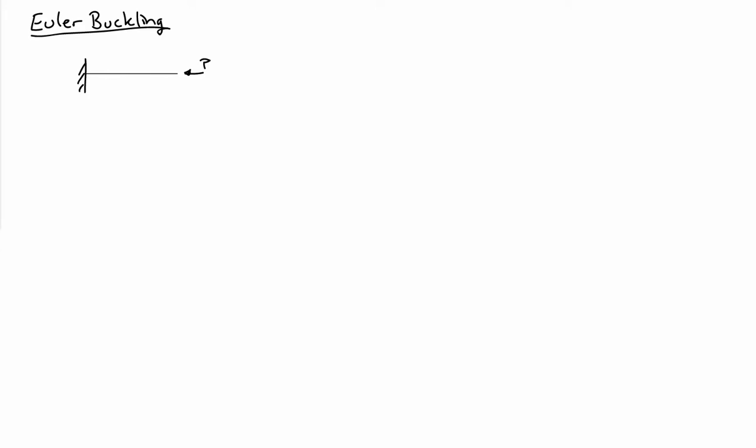Let's go ahead and try applying our notions of stability and buckling now to the case of the buckling of beams. This is sometimes known as Euler buckling. Let's consider a beam that we are applying an axial load P to, and we'd like to figure out at what load P the system buckles. This is like the demos that I did a little bit earlier, but now we're going to do the actual calculation to figure out at what load the buckling deformation occurs.